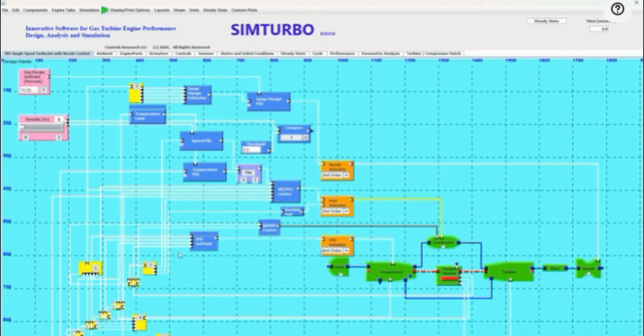properly lit. The signals for the necessary engine parameters are measured and transmitted to the control by the sensor components, represented in yellow. The necessary sensors include measurements of the turbine shaft speed, the compressor inlet temperature, the compressor inlet and exit temperatures, and the turbine exit temperature. In addition to the sensors are the other yellow components, groupers and parsers, which properly collect and disperse the sensor signals to the control.